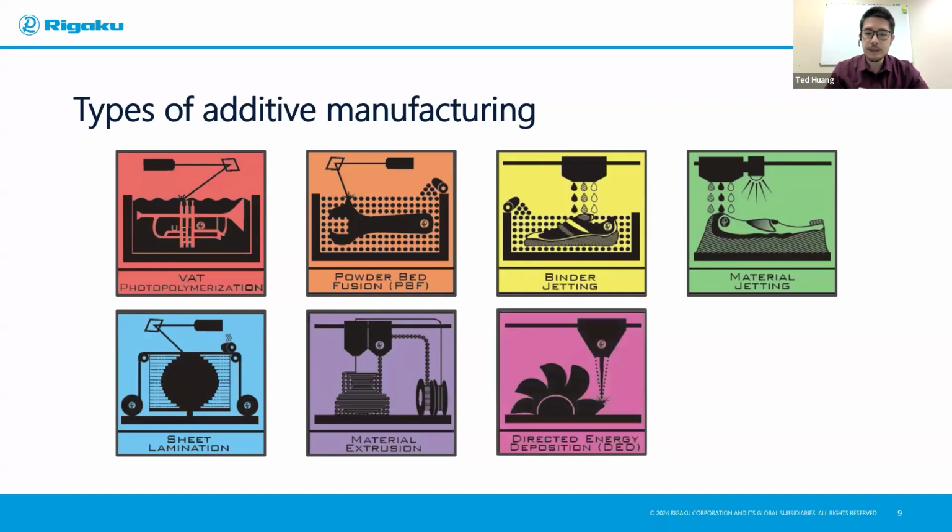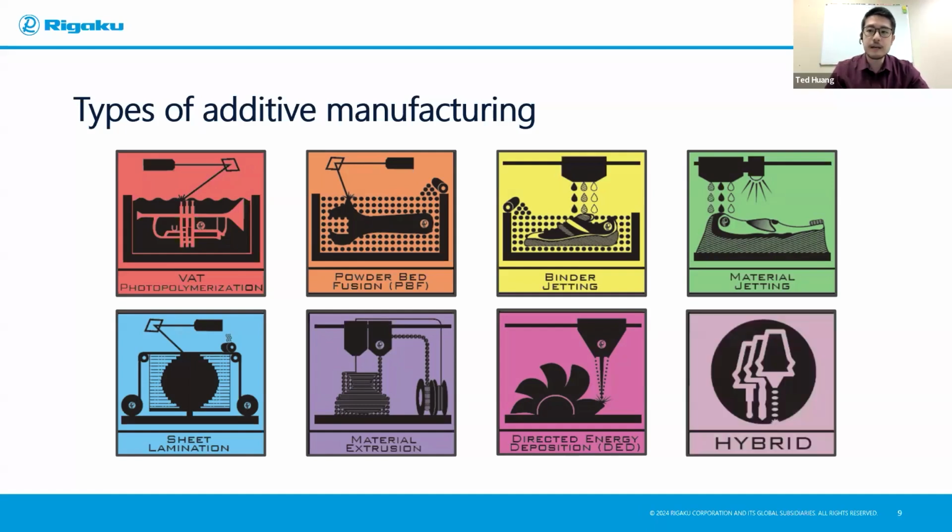And the last one, direct energy deposition, DED, it's kind of like material jetting, but for metallic powders. You throw out your metallic powder at the same time with the heat source trying to fuse it, giving you a high degree of freedom to craft the product you want. And there's a last term, kind of like an umbrella type to categorize and incorporate all types of additive manufacturing you might develop, but that is not strictly fitting into all 7 categories beforehand.